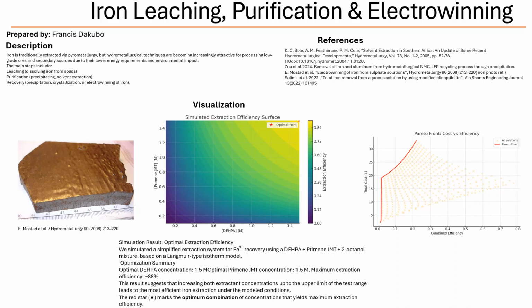Precisely. And to complicate matters further, the chemical reaction that forms goethite doesn't happen at a steady rate. It's what we call first-order kinetics. The rate depends on how much of the reactants are present. So as the reaction proceeds, the rate changes. So it's like trying to hit a moving target. In a way, yes. That's why you need dynamic optimization. You have to constantly monitor the process and adjust how much oxygen and zinc oxide you're adding in real time to get the best result.